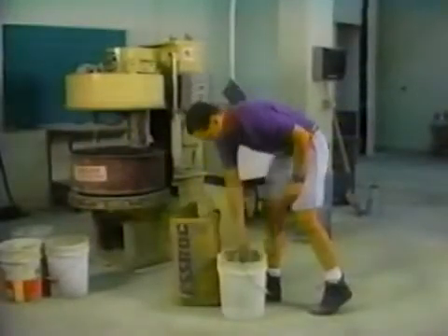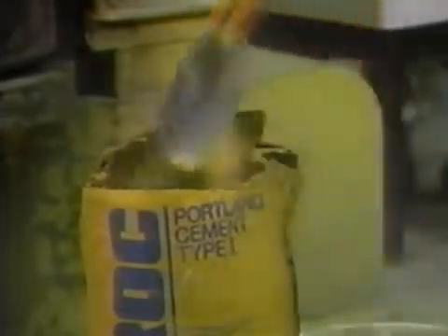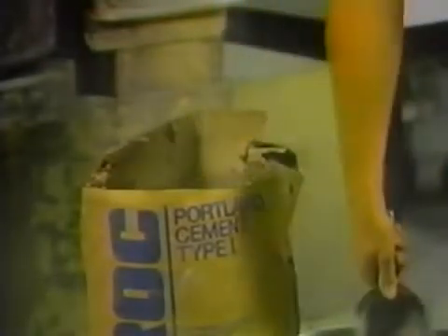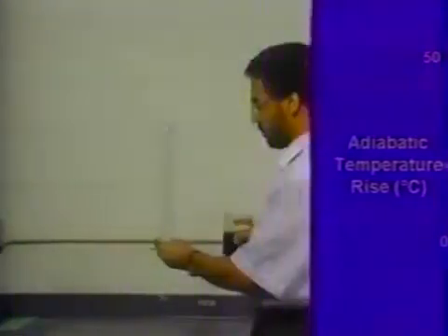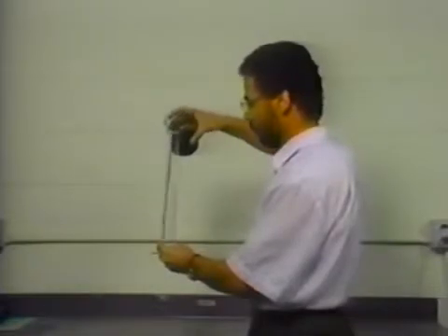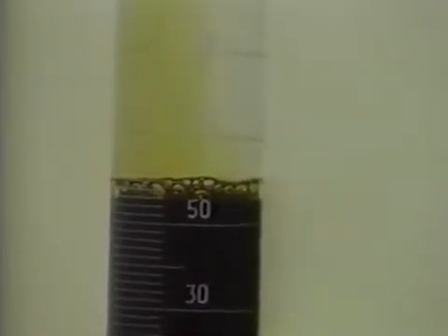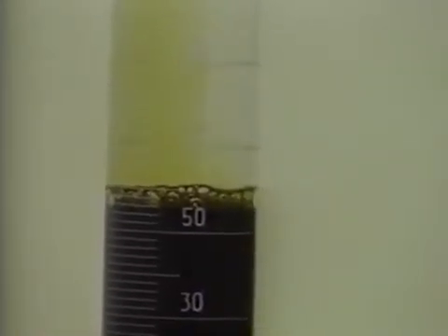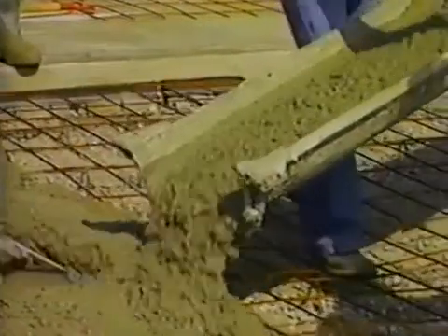Hydration of concrete can also be controlled by using different types of cement to counteract the effects of high or low temperatures in the field. For example, the use of type 3 cements counteract cold temperatures because they hydrate faster. There are also special chemicals that regulate hydration. Accelerators can be added to concrete to make hydration proceed faster. Set retarders slow hydration. These materials are widely available.